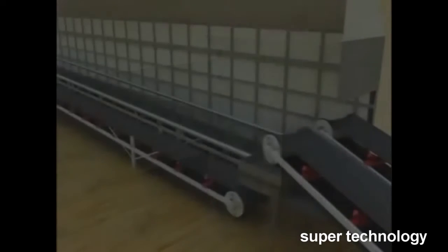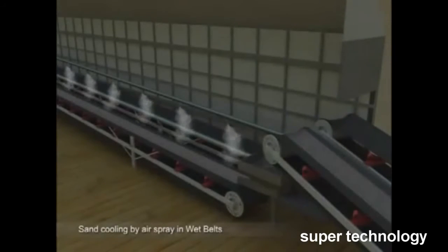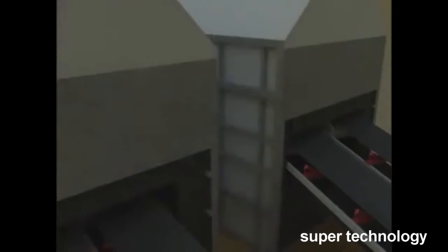A conveyor carries aggregates from the silos, one size of aggregates at a time, to the rotary feeder. The rotary feeder mechanism directs the aggregates flow to the respective conveyors and subsequently to the hoppers in the wet belt system. Here on, all the facilities are covered and insulated to avoid heat loss. The conveyors carrying aggregates of size 10 mm and sand pass through a chilled air blast, while larger aggregates pass through wet belts with chilled water spray with temperature of 2 degrees centigrade.